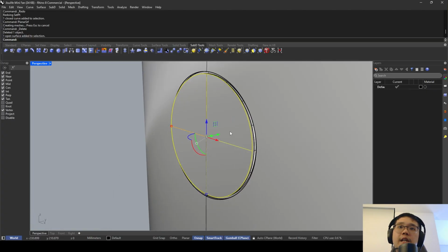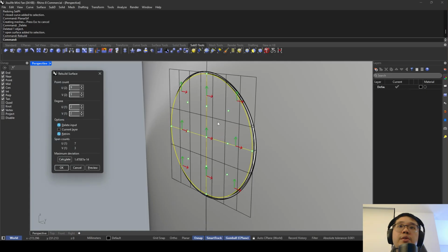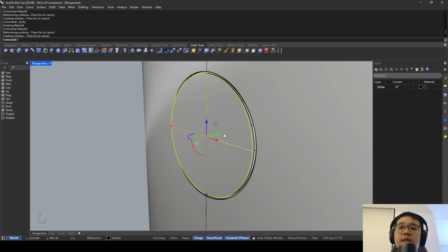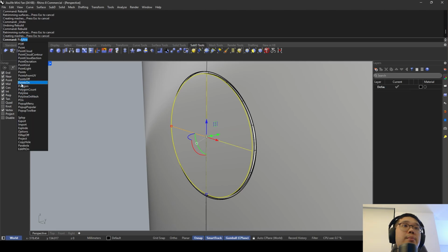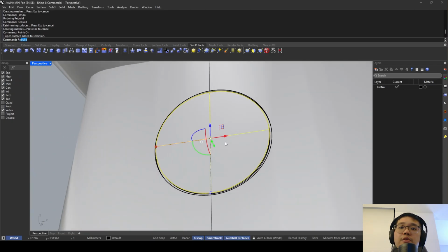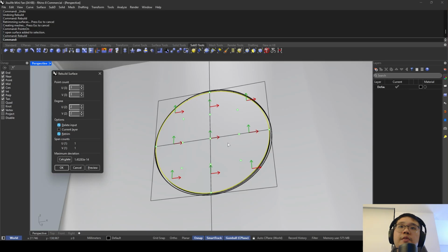And to create a concave, I can do a rebuild. Click OK. Not really. We can do a rebuild 3x3 and I'll see how it looks. I can do points on, command points on. So 3x3 means that when I do a rebuild, I can rebuild the surface, so I can sort of subdivide the surface. I want to just subdivide it enough to get this point in the middle. So 3x3 usually means that there's 3 and 3 dots here.